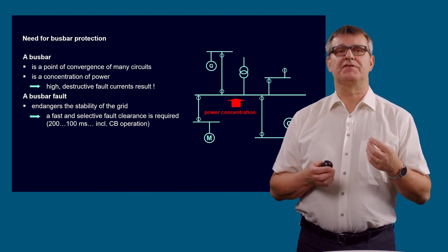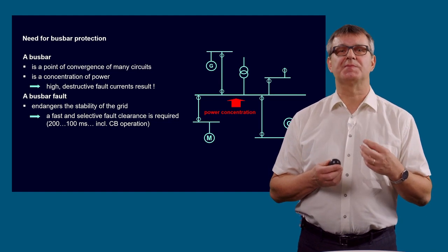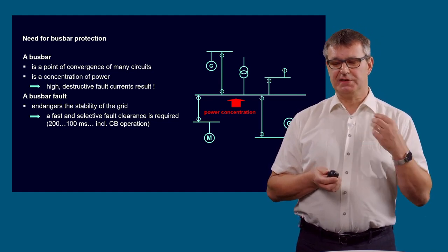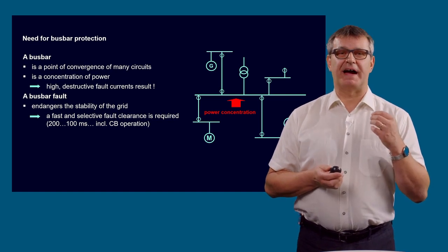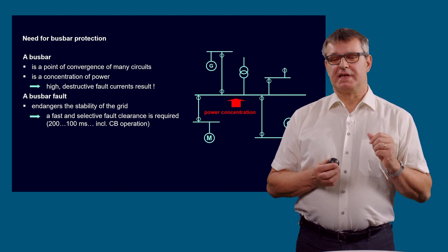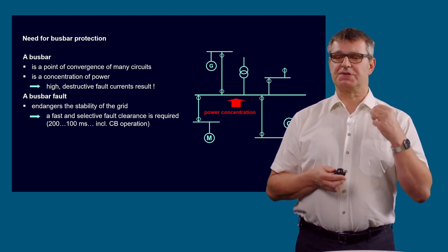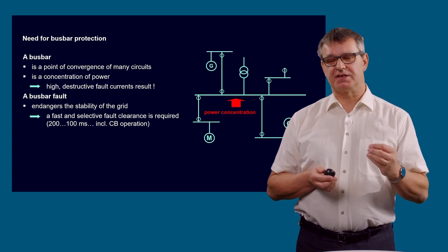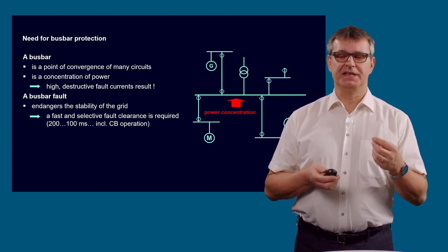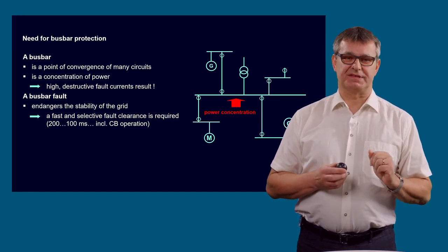But typically for extremely high voltage busbar protection, the requirement from the utilities is that the device itself, without the delay time of the circuit breaker, clears the fault in sub-cycle. That means to detect the fault within one sub-cycle and at least to activate the binary outputs of the device itself.